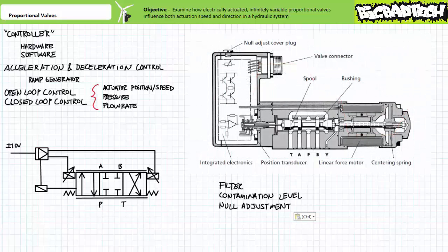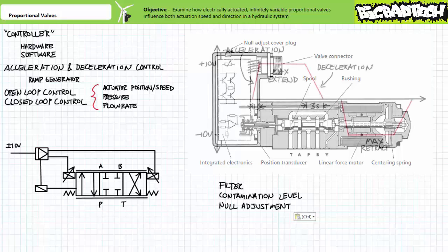Additionally, proportional valves employed with actuators positioning a static load often necessitate a means of null adjustment, where null adjustment means the purposeful shift of the spool slightly off-center when applied voltage is 0 or null. This tiny shift prevents the applied load from drifting over time. Changes in temperature or pressure, or simply valve age, may cause the null position to drift slightly. Null readjustment may be a part of regular service for systems employing proportional valves.